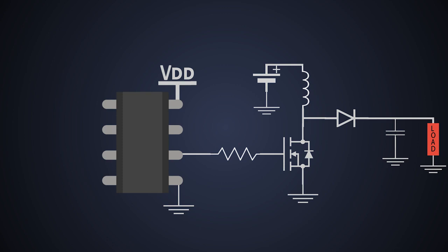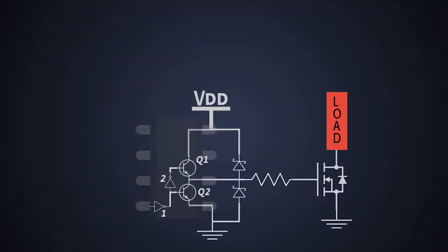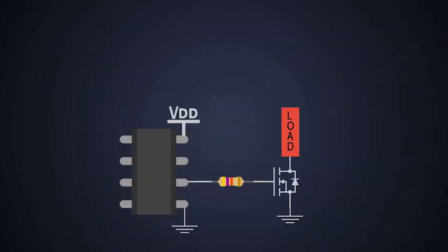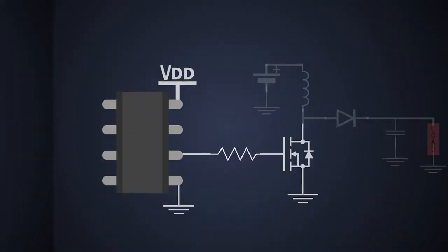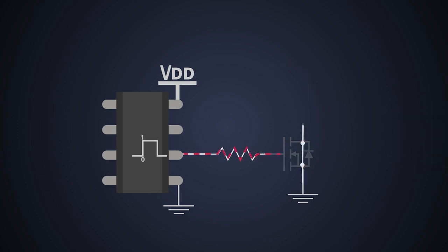We have seen in our previous video about the limitation of switching speed and the significance of the gate resistance. Please click on this card above to know more about it in detail. We can apply a higher permissible voltage across the drive output impedance and the gate resistor to get the optimum turn-on speed. So usually the obtained turn-on speed while switching is sufficient to drive the MOSFET. But the situation is very different at turn-off.